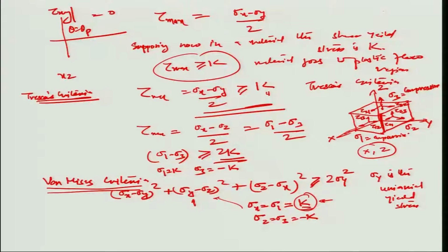So having said that, now in the plane strain case we will not consider any kind of stress along the y direction, because obviously the dimension is too big for any marginal strain to be recorded in this particular direction. So we can call sigma y equal to sigma 2 in this particular case to be equal to 0, okay. So having said that, if I calculate the criteria corresponding to which the von Mises criteria would hold, or plastic flow would actually start happening, we substitute all these values back into this equation.